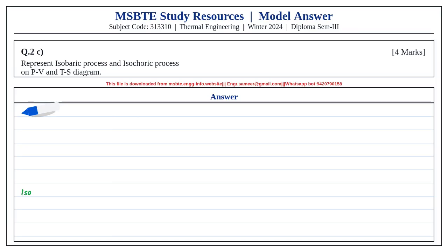Substituting values, Q by A is equal to 250 divided by 0.02 by 58 plus 0.005 by 0.116. This gives 5754 watt per square meter. Therefore, the rate of heat flow is 5.754 kilowatt per square meter area.